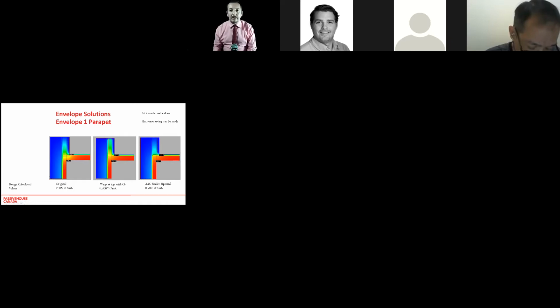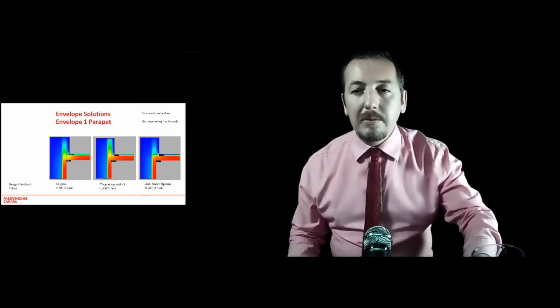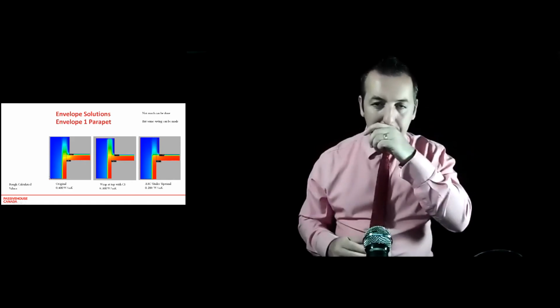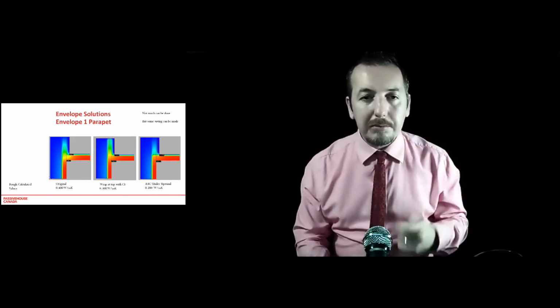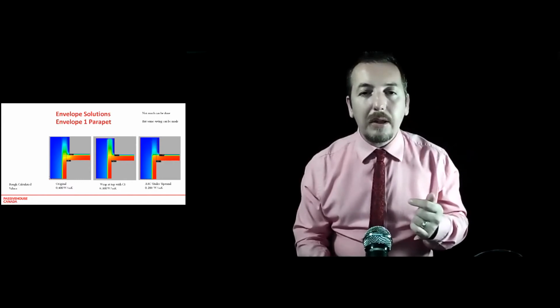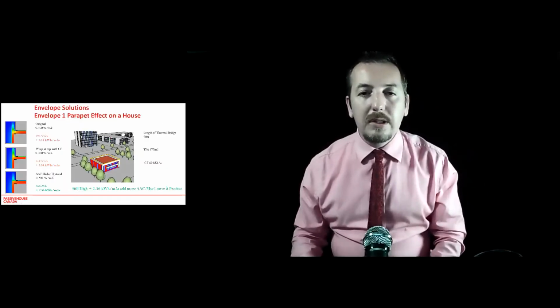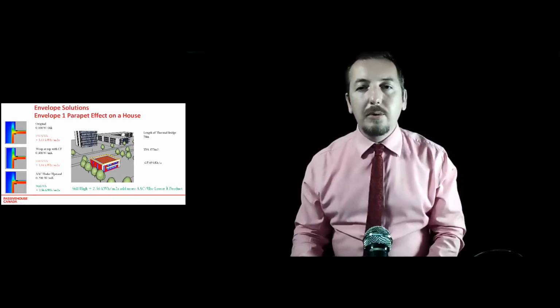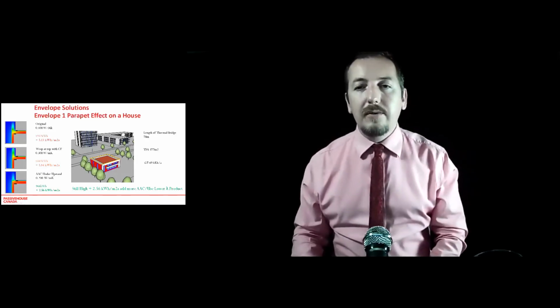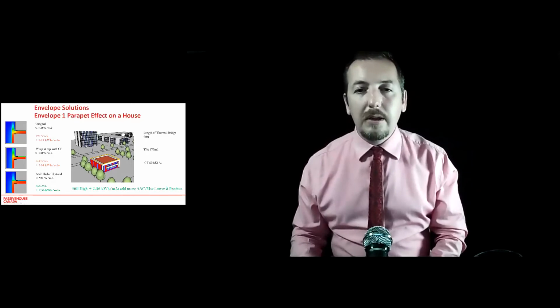Now, if I had covered the top and broke it and maybe used a better thermal break like cellular glass or a couple of rows of aerated concrete, I'd have maybe got this down to something more like a passive house psi value. But nevertheless, I took that value and I applied it to a small building. Now it says a house, but we've got a treated floor area here of 377 square meters. That'd be more like the house I'd want if I won the Euro Millions.